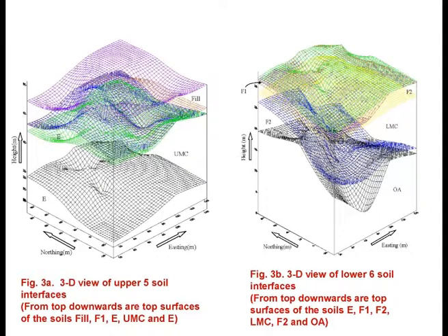And one of the things we did in those days, now in Plaxis is very straightforward. You can upload the boreholes. But in those days, there was no such thing. So as a result, what we did was that we took all the boreholes and we used surface mapping software to layer out the top and the bottom of each soil layer, and then we uploaded it onto the mesh using a program we developed ourselves. So it's quite a complicated thing, you know.